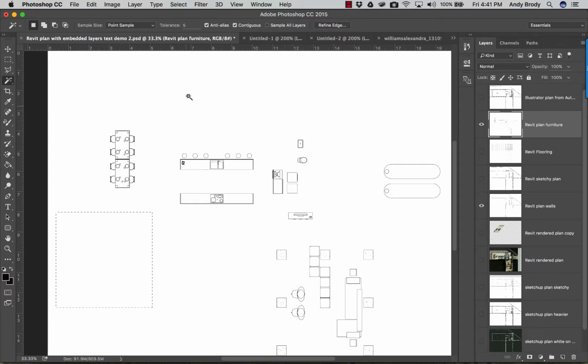And the way it works is when you click on a pixel, it tries to select every pixel that looks just like the one that you clicked on. So if I click over here, this is a white area. Now, right now, when I click on that, what you'll see is it's basically selected every area that touched that original pixel that is white. That's because I have this contiguous button checked. If I didn't, and I went here and did this, now it would select every white pixel on the screen. I could also sample all layers. I absolutely don't want to do that either.